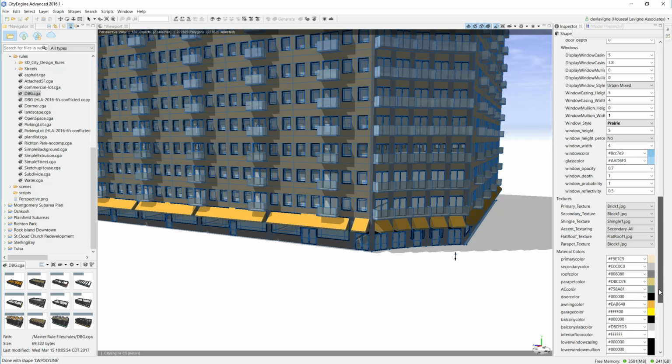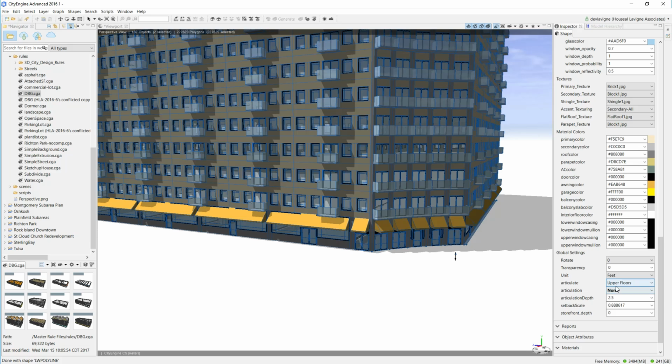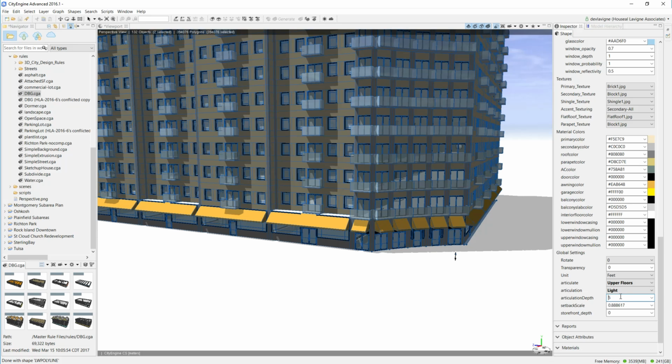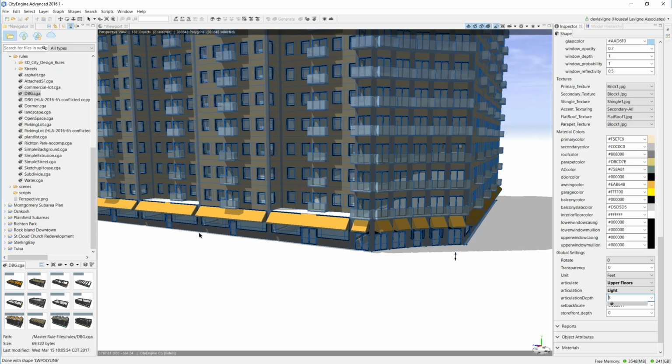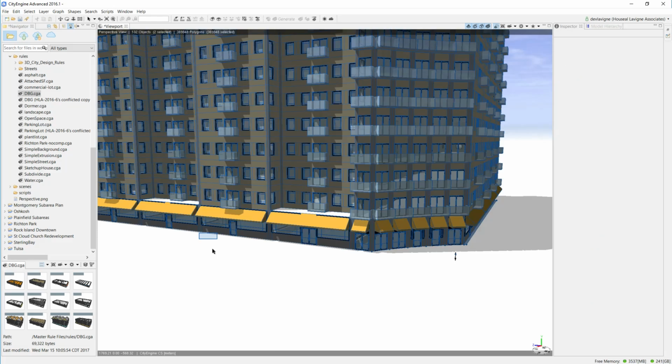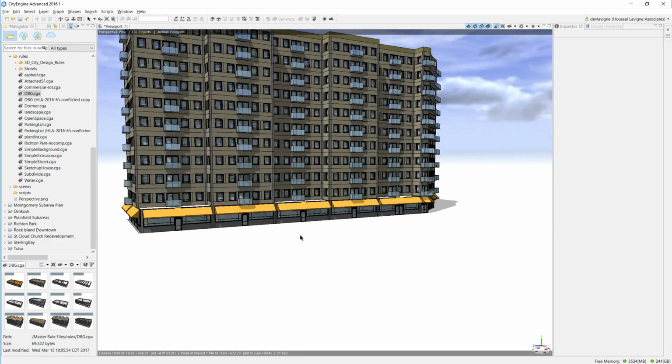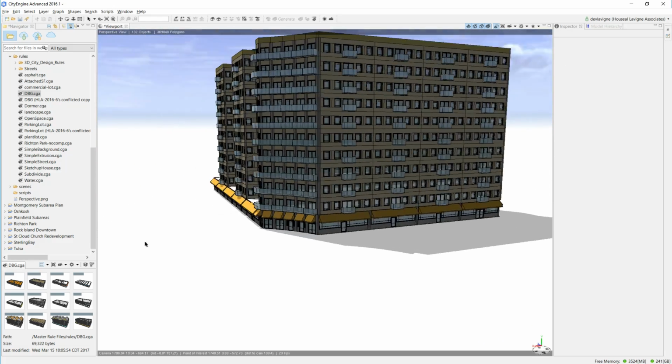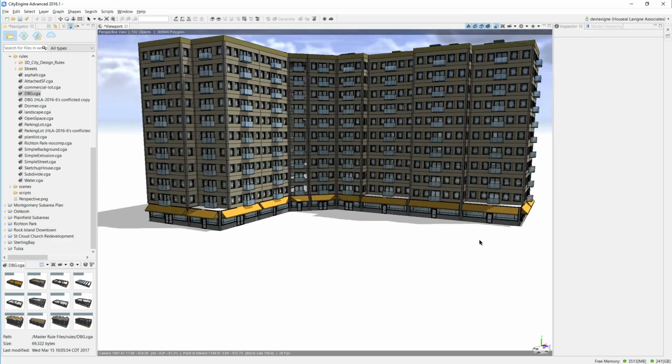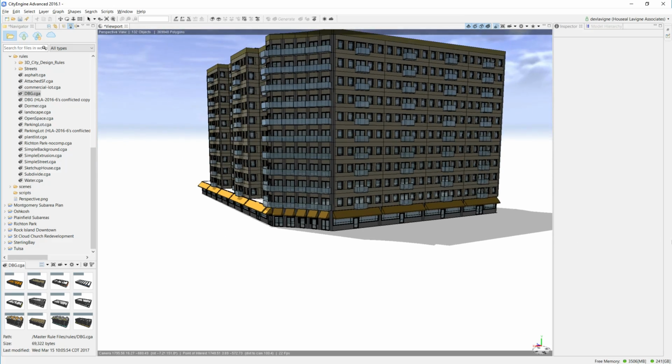You get a tall building like this, it starts to look like a gigantic wall or mass. You want to articulate it. The rule that we have here, we can start to articulate that facade. So we can set it back 2.5 feet, or if we wanted to set it back 5 feet. And if there's enough space in there, it'll draw the window for us. So really great rule, saves us a ton of time, allows us to quickly generate buildings that we can now move back and forth between CityEngine and SketchUp.